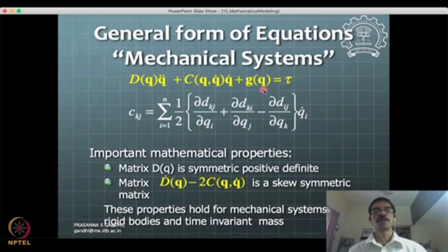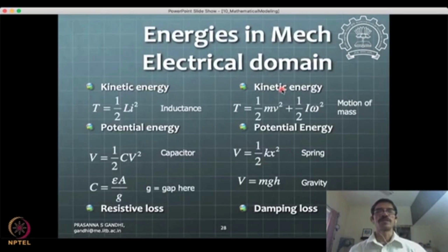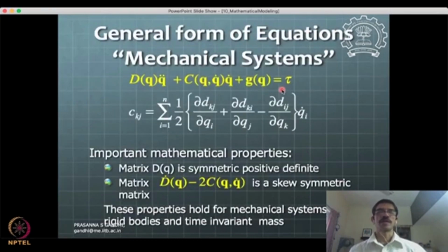If the generalized coordinate is a linear quantity, like x, then this will be a force. If the generalized coordinate is theta, a rotation quantity, then this will be a torque. These torques in the direction of generalized coordinates need to be added, and the damping and other terms can be added into those parts. That's how we'll proceed with the mechanical system derivation.